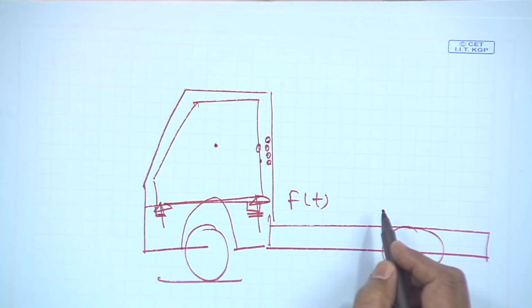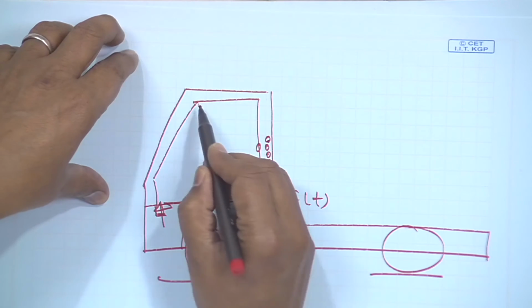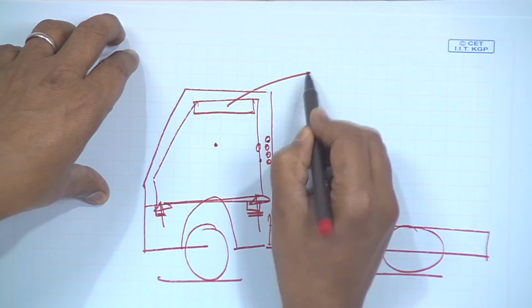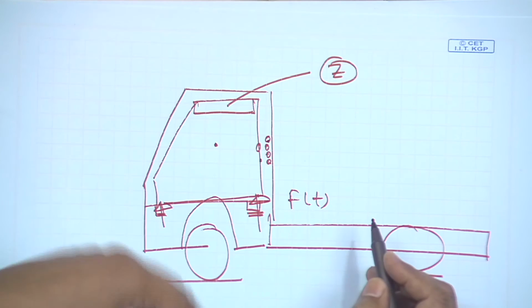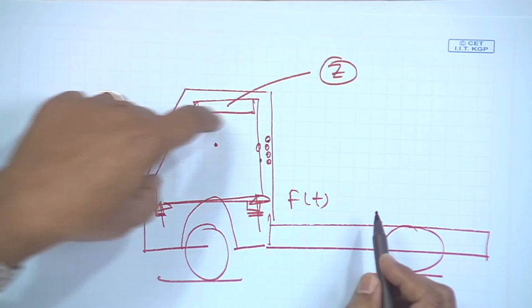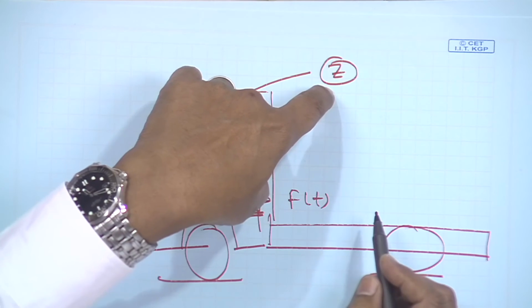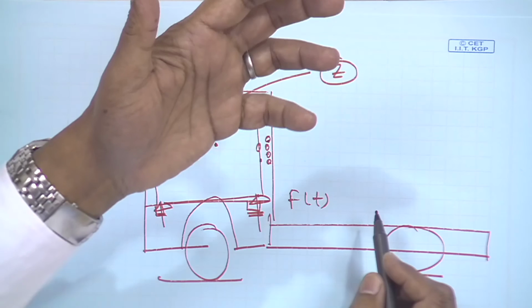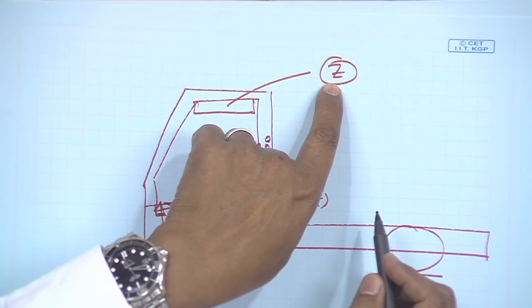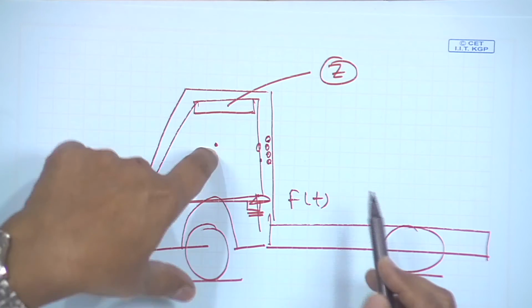In this case it happens to be the driver's right ear. In the boundary element method, if I have in my cabin, say, a headliner, I could give the impedance of that headliner as a boundary condition at the roof location. I could play around with these impedances. For example, if I want to put in higher absorption material, I can change this impedance and predict the noise at the driver's right ear location.